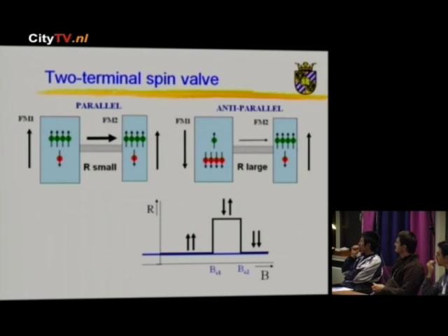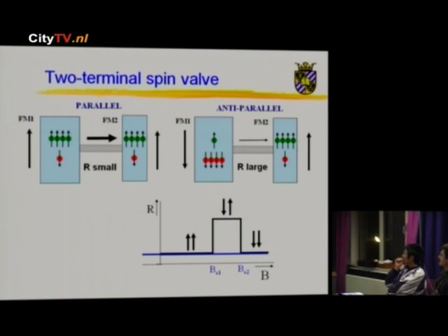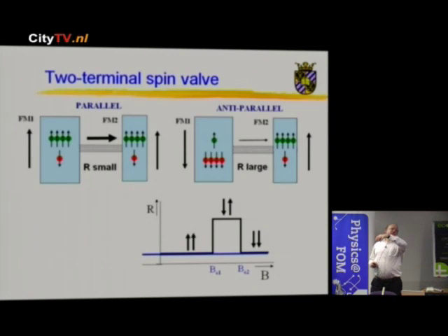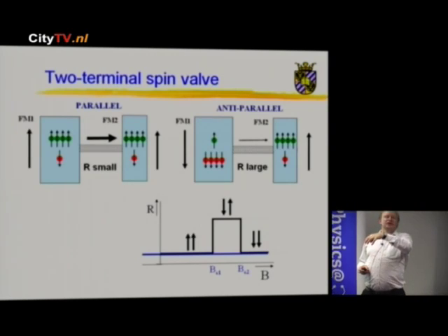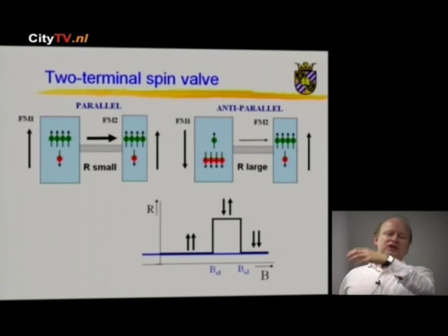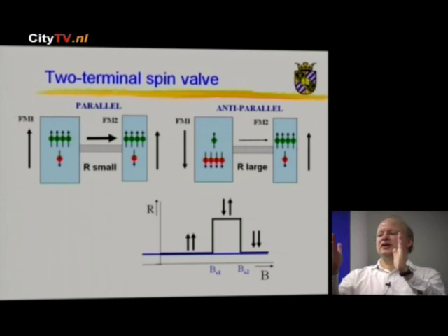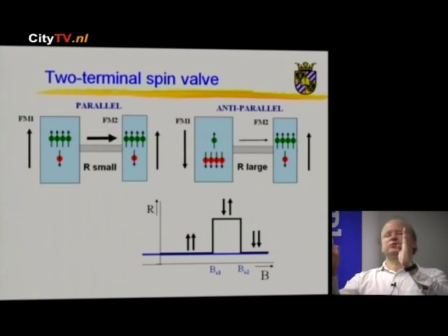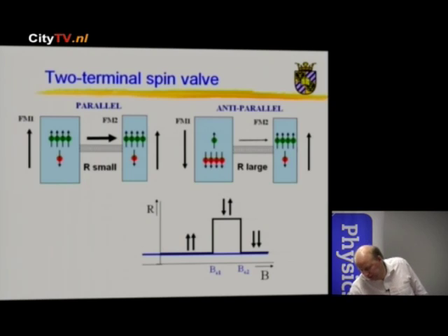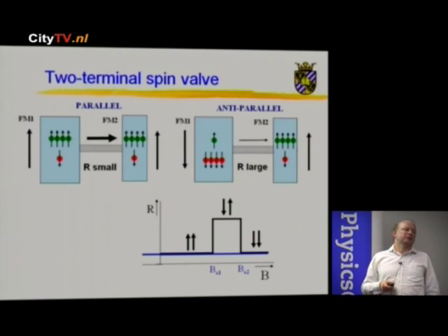You can remember. Okay. So there are two effects which can happen if you put an atom or molecule on top of your graphene. One of them is charge transfer. There could be some charge transfer between the molecules, so it's actually doping. So obviously that will change your resistance. The second one is that it induces scattering. Scattering, of course, always increases the resistance, and if you include doping, well, it depends where you are. If this is your Dirac point, neutrality point, if you sit here, then clearly, if the doping goes this way, then you reduce the resistance. If you go this way, you increase it. So these are the two effects which you could also use to distinguish the type of molecules.